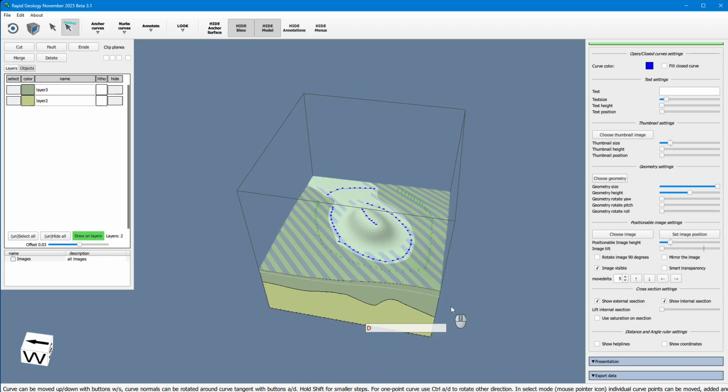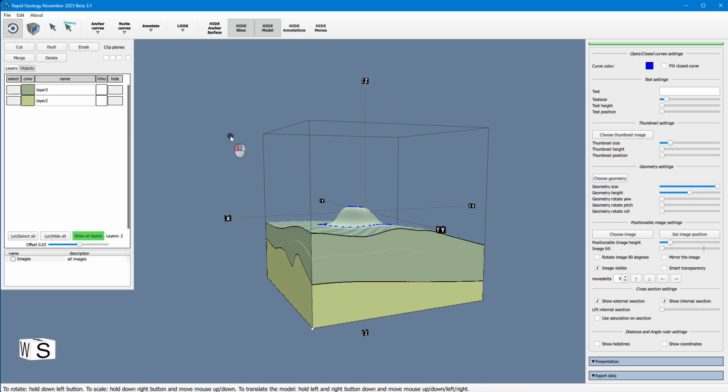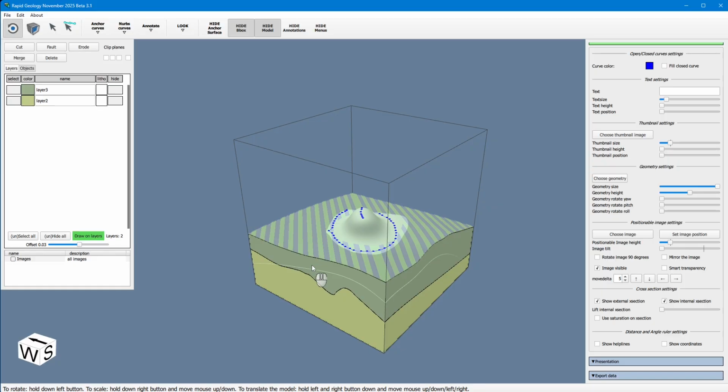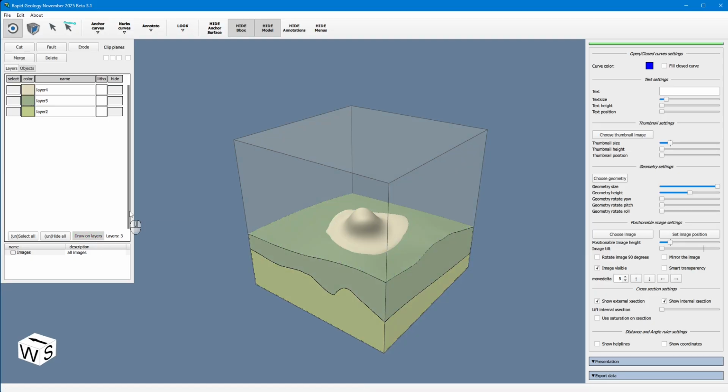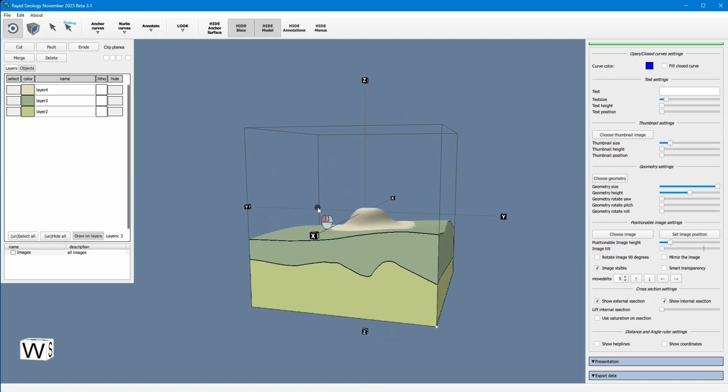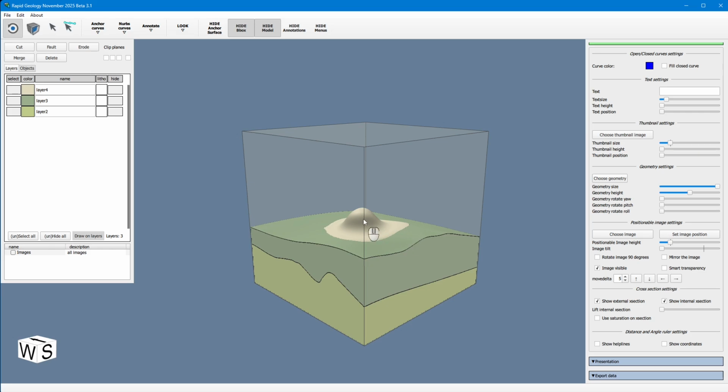You can also rotate the normal and also here, move it down. Then you get something like this, and then when you press cut and then turn this off, you get a new shape that fits the terrain, which is flush with the normal and then changes. If we hide it, it looks like that.